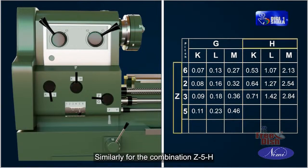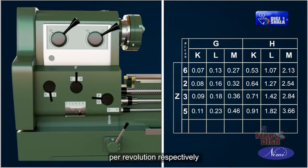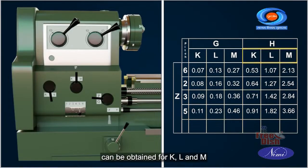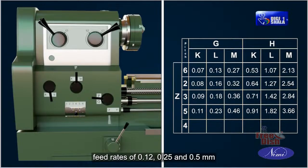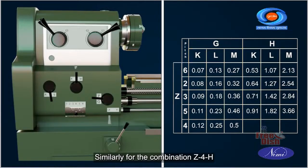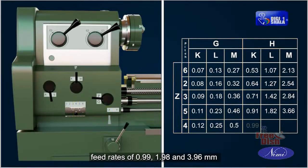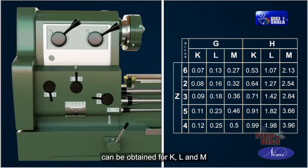Similarly, for the combination Z5H feed rates of 0.91, 1.82 and 3.66 mm per revolution respectively can be obtained for K, L and M. For the combination Z4G feed rates of 0.12, 0.25 and 0.5 mm per revolution respectively can be obtained for K, L and M. Similarly, for the combination Z4H feed rates of 0.99, 1.98 and 3.96 mm per revolution respectively can be obtained for K, L and M.